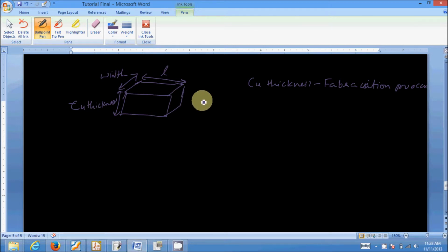That is again determined by the spacing, so length is not of much concern. We usually have components closer to one another. So the only parameter that remains to be seen is the width of the traces. Now this is in general for digital designs with not a lot of complications.